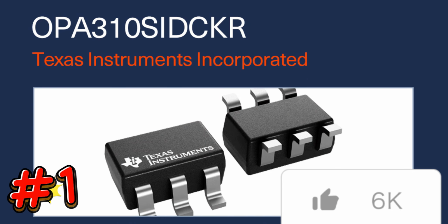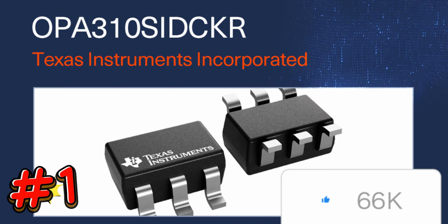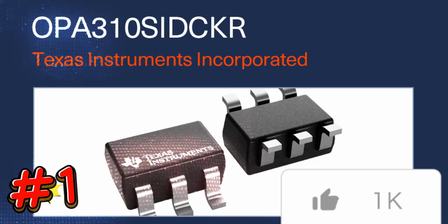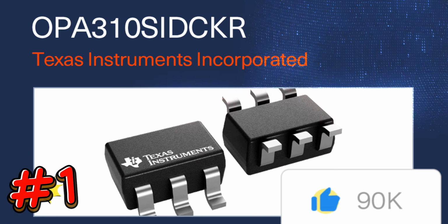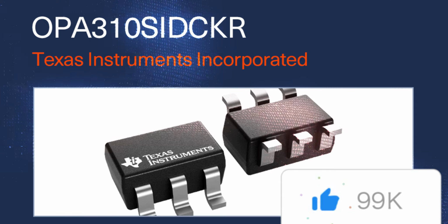The simplified design features an integrated RFI and EMI rejection filter with no known phase reversal in input overdrive conditions. As such, the op-amp also delivers superb AC performance with a gain bandwidth of 3 MHz. Designers can achieve improved performance and lower power consumption when utilizing the OPA310.